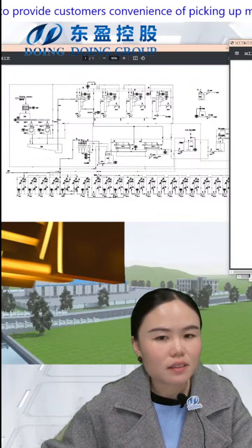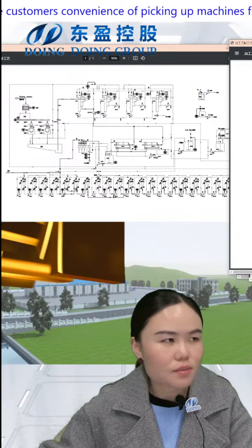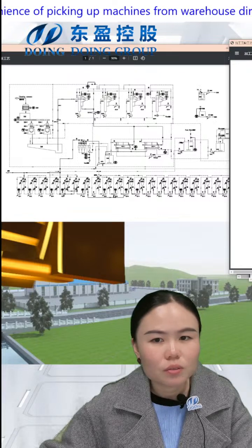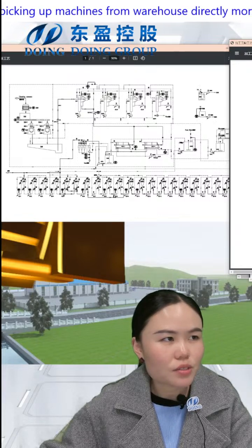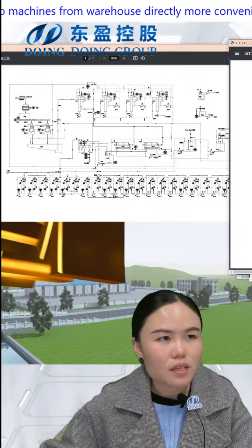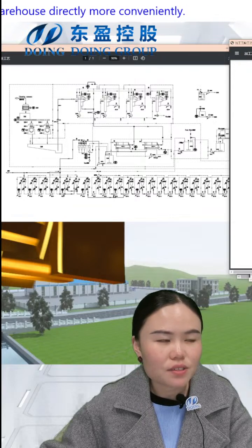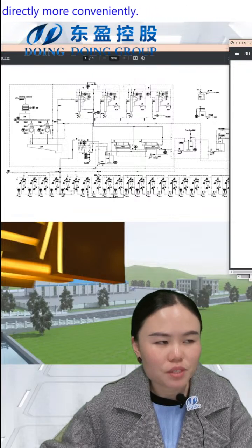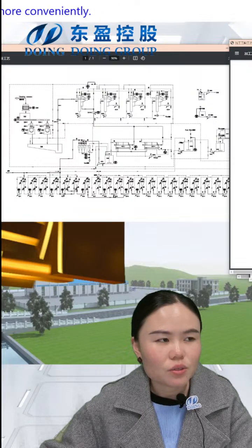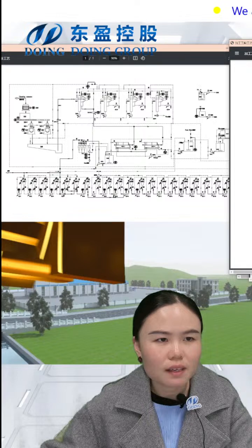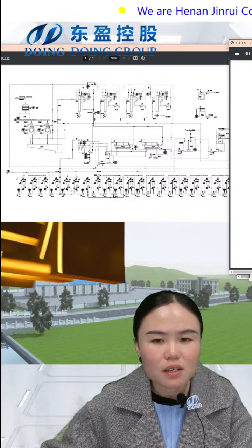So firstly, use the cutting machine to get the small cassava pieces, and then use the rasper to get the fine cassava mesh. We'll go through the centrifuge sieve machine to separate fibers, and after that go through the desanding machine, and then go to the hydrocyclone station. This hydrocyclone station will remove protein and cell liquids, and after that, this purified starch milk will be pumped to the dehydration machine.